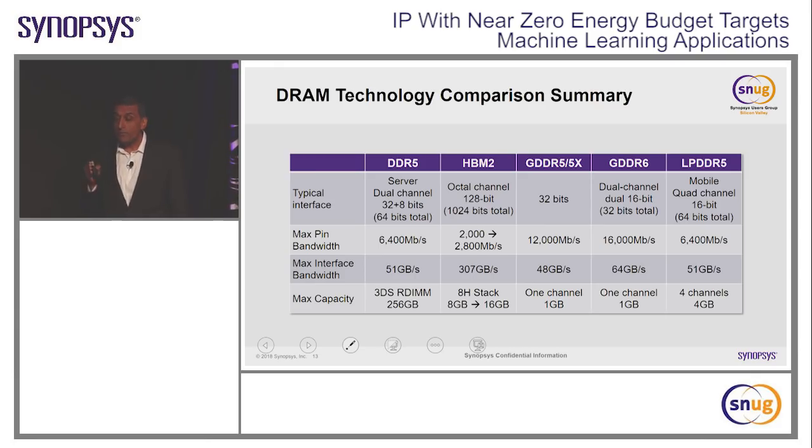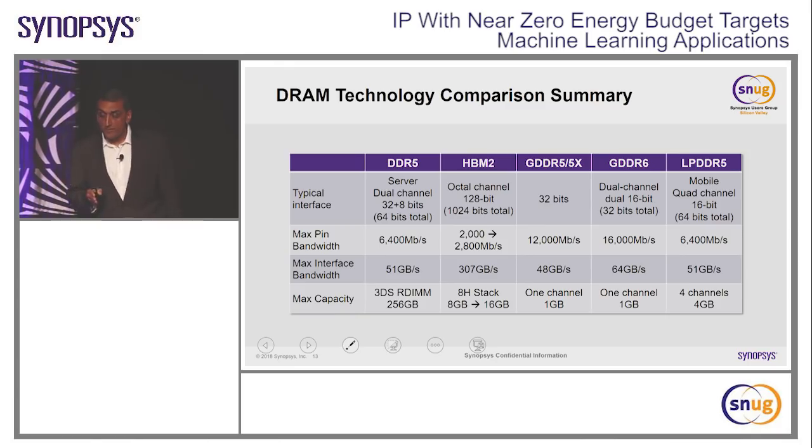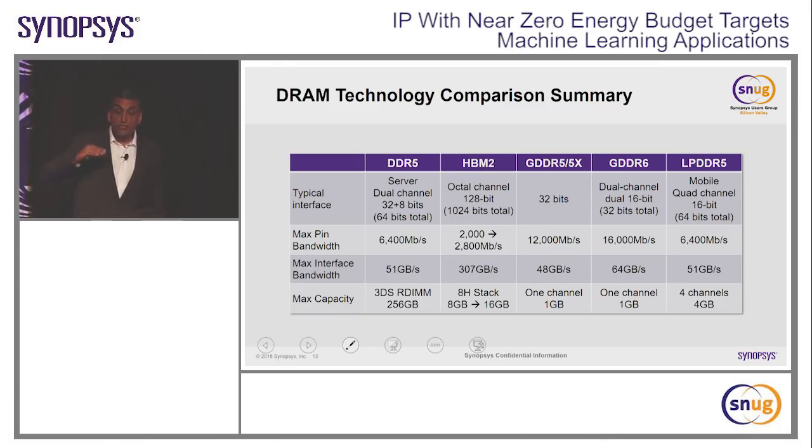On the other hand, high bandwidth memory works very well in parallel computing applications. It's used for specialized accelerators for deep learning. You can connect the HBM to a host SoC by a 2.5D interposer. Okay? We'll get into some of these details later. HBM is a very wide bus operating at modest data rates. 1,024 data pins are available per HBM stack. You can stack these up to 8, which increases your capacity. It's a point-to-point interface with double data rate signaling. You add capacity by stacking the DRAM die using through silicon via technology.